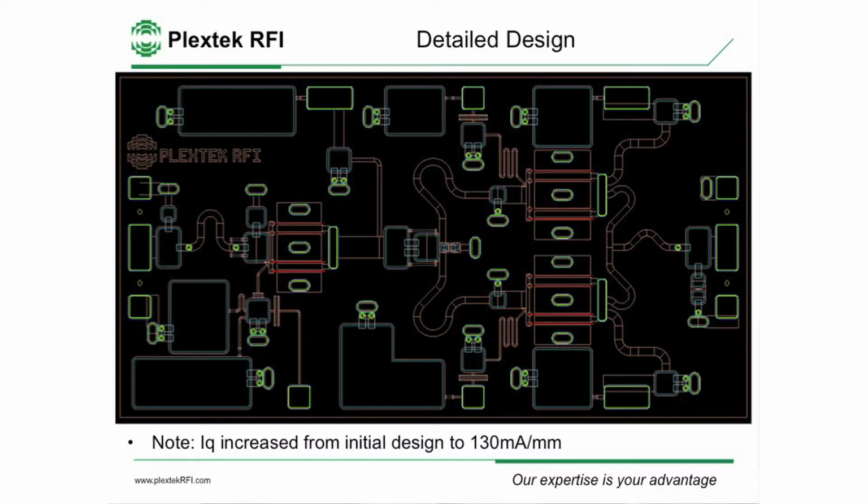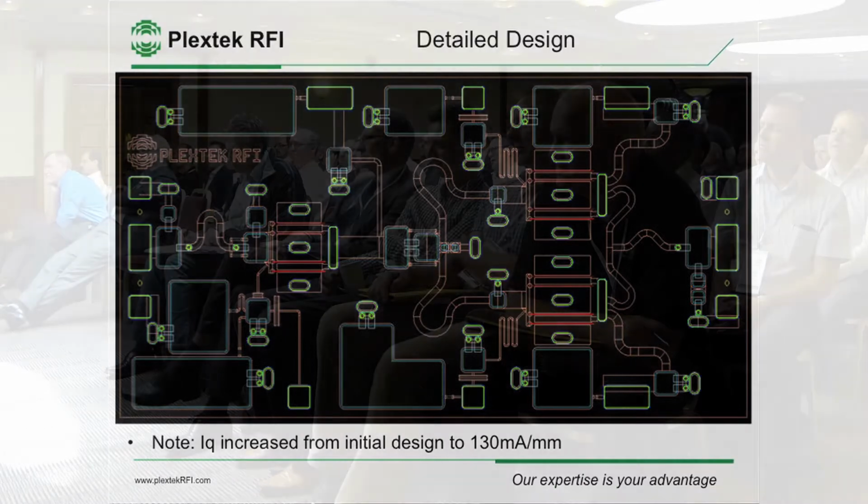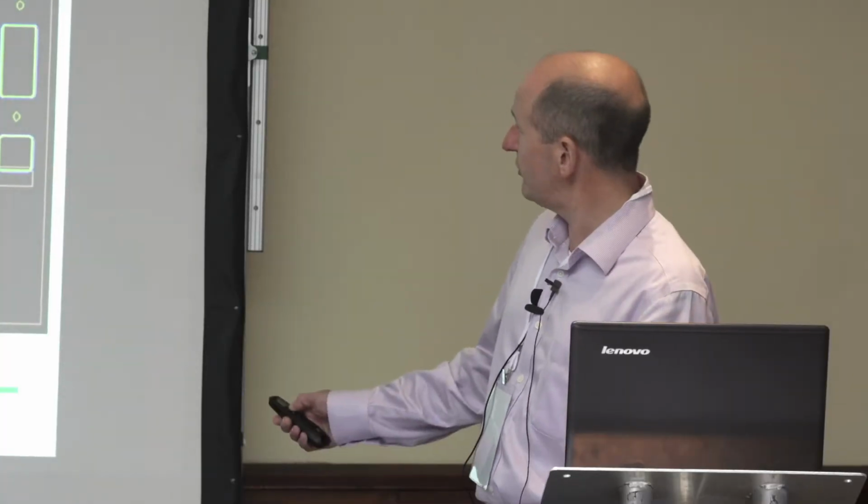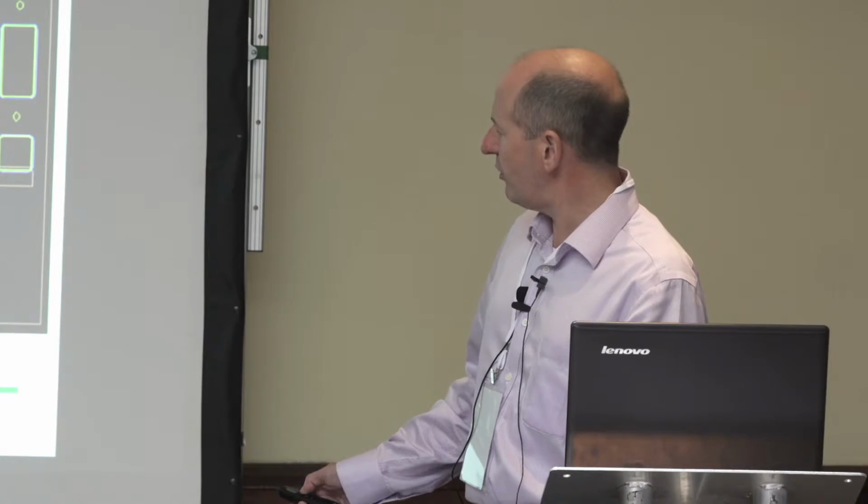Now, any IC shouldn't require microwave decoupling off chip. You've done something a bit wrong if it does. All your microwave decoupling, all your RF decoupling, that should be on chip. It's your low frequency decoupling you want off chip. We've got some RC decoupling here, and what we tend to do is fill in the spaces, like we've done here, to put in as much capacitance as we can without excessively increasing the chip area.